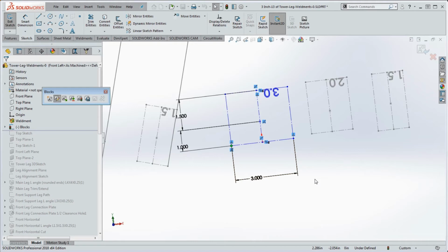When you're in SolidWorks, sometimes you get lost in your model. If you go into the graphics area and it's the first time visiting that, you really don't know the size of some of the elements you're looking at. But this gives you a very quick visual reference in here because it's going to be pink in the background that you're supposed to have a 3-inch structural member in here. So if you put in a structural member that exceeds this on one side or the other, if it's too small or too big, you can tell right away that you don't have it correct. And number two, another advantage of having that text number in there is you have the capacity to look at your model real quick and say, okay, that's a 3-inch, that's a 2-inch, that's a 1.5 inch, and it gives you a pretty good idea what you're looking at just right off the bat. Again, avoiding the feature manager over here.